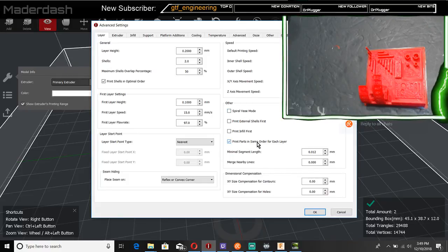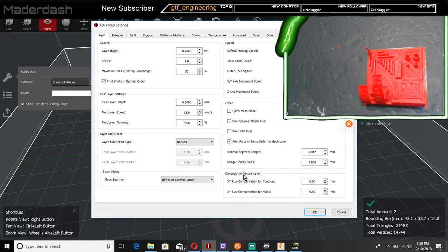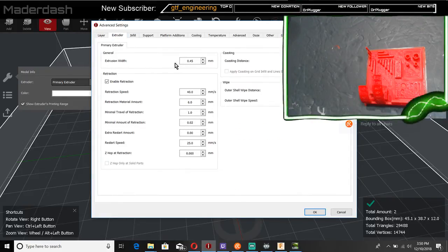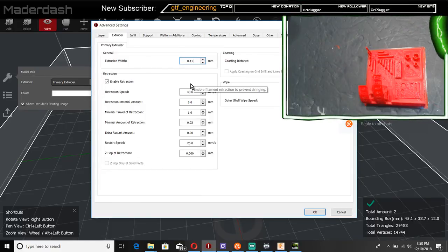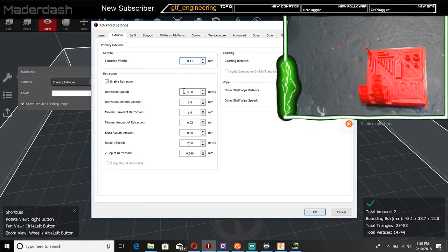Let's see, print parts in same order for each layer, yes. Extruder, oh, we don't need that. We need to change that down to 41. Yeah, 41. Enable retraction, yes. 40, no, let's cut that down to 30.